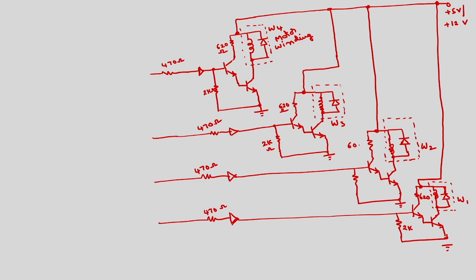On the other side we have to use the 8255. So, these are all called buffers. There are 4 buffers. We know the buffer increases the current capacity. I am going to connect this to one of the ports of the 8255.